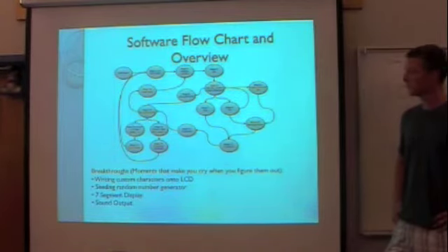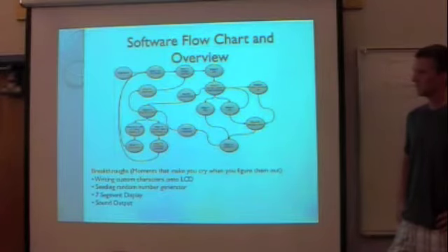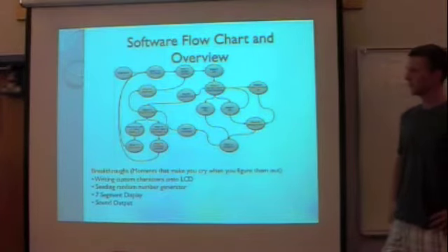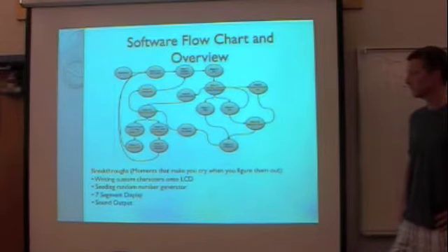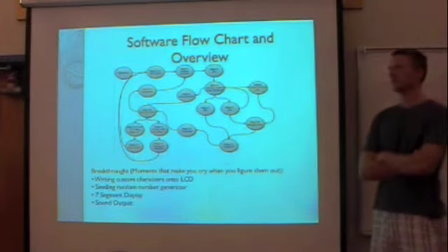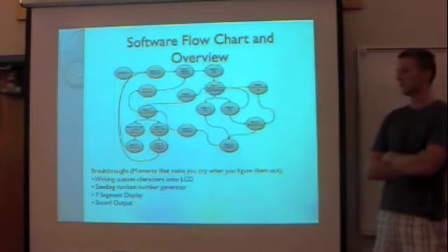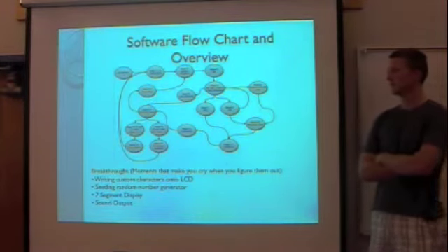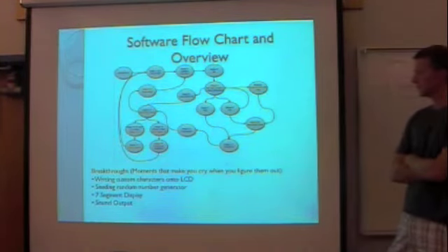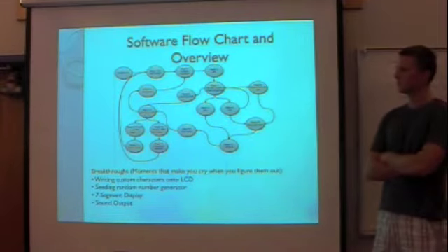We found out that we had to seed the random number generator, because otherwise every time you program the game, you would always get the same cards. To get around this, whenever the user presses the button to continue, it takes the value in the timer status register and uses that to seed the random number generator. After that, it goes into stage 3, which initializes variables to start a new hand.